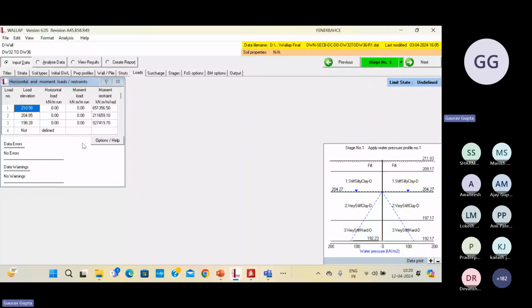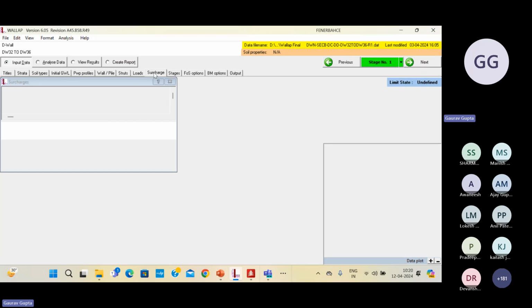So we have to provide the parameters similarly. For every slab level, like the roof slab, concourse slab and base slab, we have to provide the moment restraint after calculating from the structure. Now this will provide the rigidity and create a fixed end moment in the system.